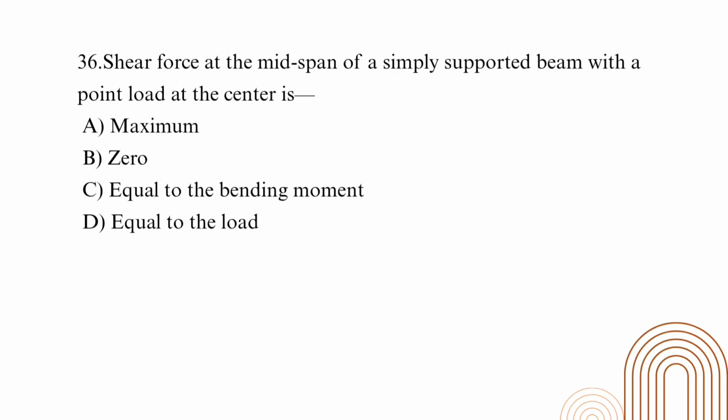Now the next question is question number 36: shear force at the midspan of a simply supported beam with a point load at the center is, and options are A, maximum, option B, 0, option C, equal to the bending moment, and option D, equal to the load. And the correct answer is option B, that is 0. The shear force at the midspan of a simply supported beam with the point load at the center is 0.